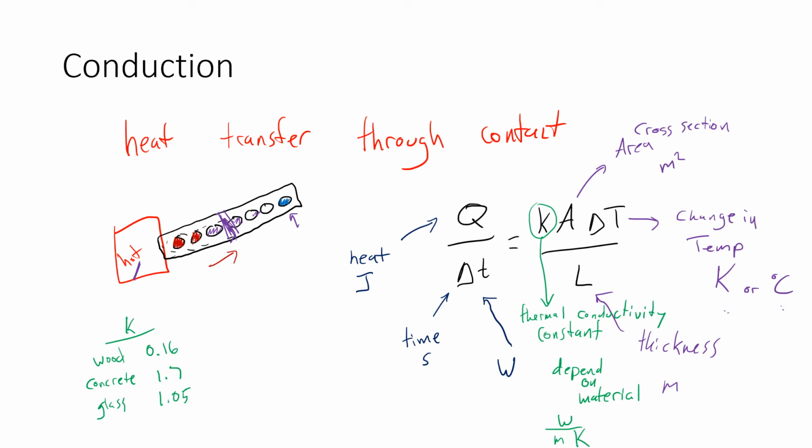And so it's a little bit of a better insulator than wood, than concrete, but not as good as wood. And finally, steel. What would you expect for steel? Would you expect a big number or a small number? What do you think? Steel is going to have a very large number. It is 17. It's a whole number. So it conducts 17 times as much heat as glass does. It's a metal. Should make sense. It's a good heat conductor.